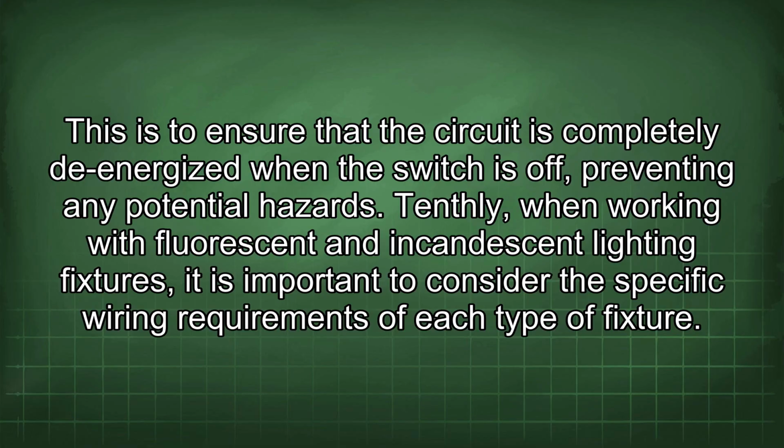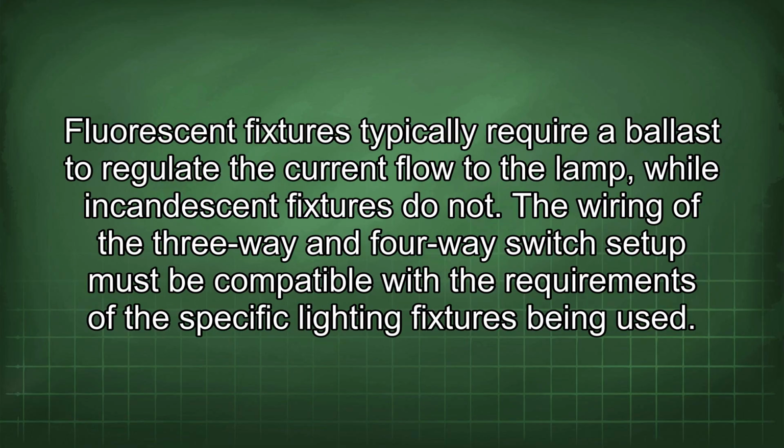Tenthly, when working with fluorescent and incandescent lighting fixtures, it is important to consider the specific wiring requirements of each type of fixture. Fluorescent fixtures typically require a ballast to regulate the current flow to the lamp, while incandescent fixtures do not. The wiring of the 3-way and 4-way switch setup must be compatible with the requirements of the specific